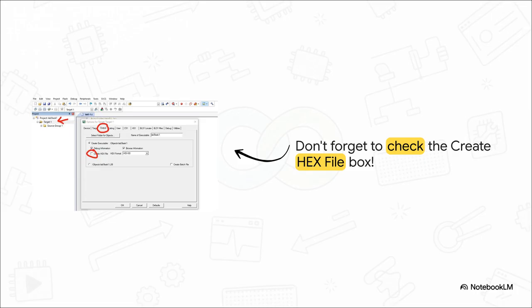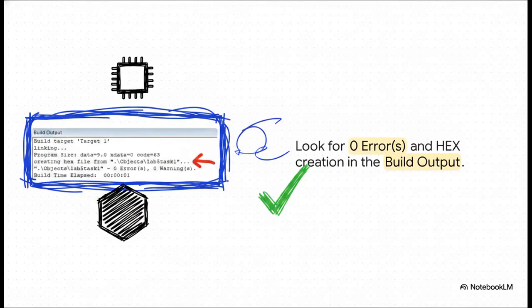Because if you skip this, Keil will gladly compile your code, but it won't generate the actual file Proteus needs. Your bridge will be missing. Okay, so once you've checked that box, hit the Rebuild button.